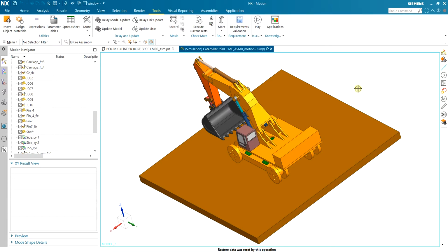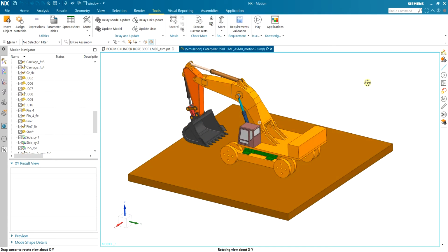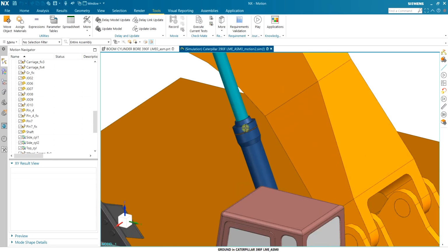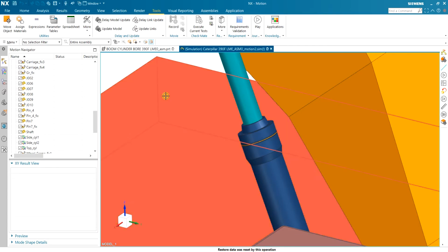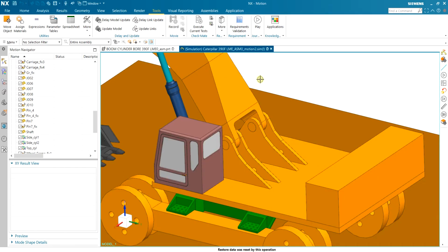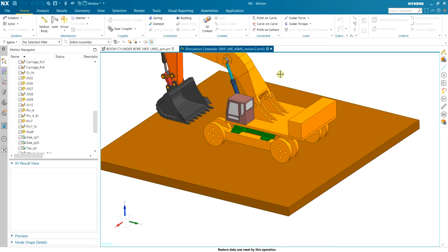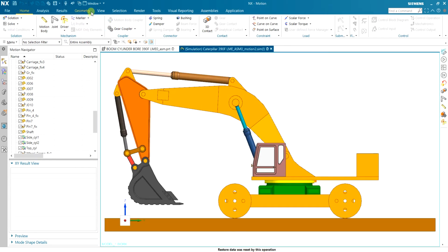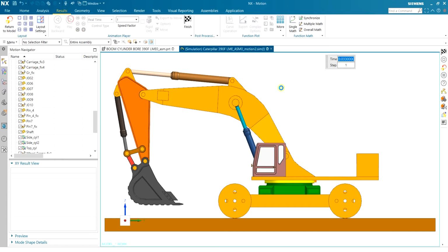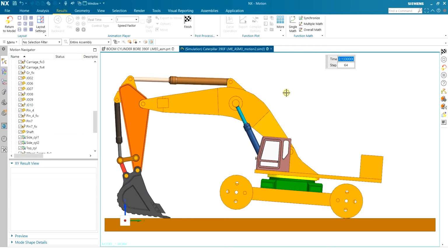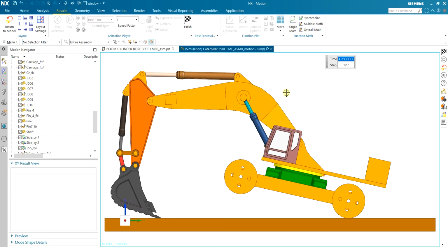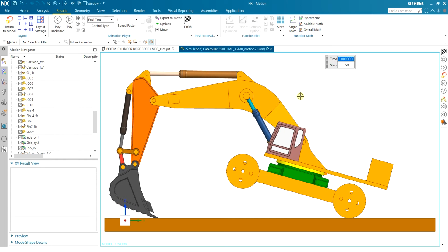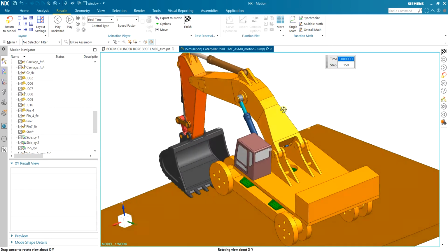Hi, today I want to show the procedure of designing bolts for a hydraulic cylinder to keep the sealing. Through that, first I need to find the pressure acting on the hydraulic cylinder, and I have a very simple example here. I have a very simple loading which is being generated when the excavator is lifting itself up.